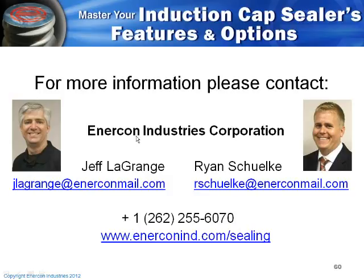The answer to that question is, if you're using the all-in-one sealing head with our Super Seal lineup, the answer is yes. The all-in-one sealing head works in a way where we have bands of closure sizes that you run. If you're running between a 20 and a 38 millimeter closure, it's typically parallel to the conveyor. But as you start to get wider than that, you start to pivot the coil. And essentially what we're doing is we're widening the effective field.